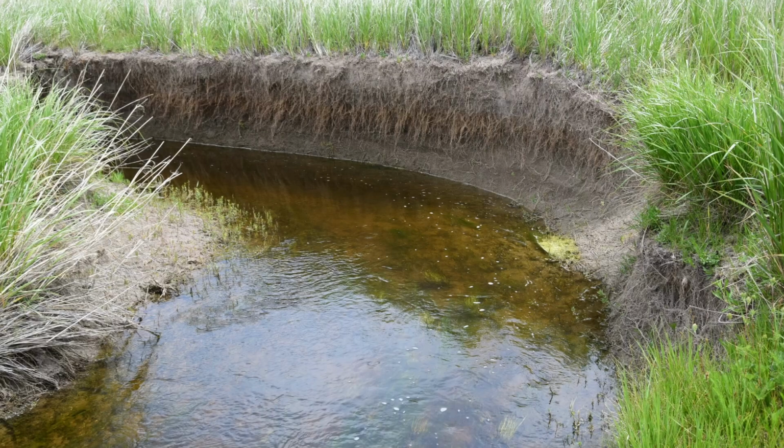The exposed roots in the channel show that erosion is taking place. The erosion is caused by head cuts advancing into the wet meadow. The head cuts are causing a deepening and a widening of the channel. The water flowing in the stream channel is from the large area of wet meadow wetland that's being drained.